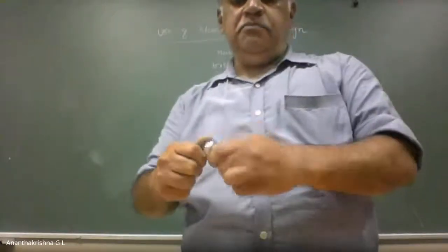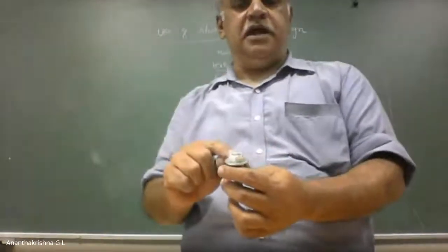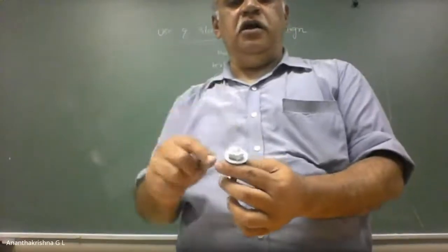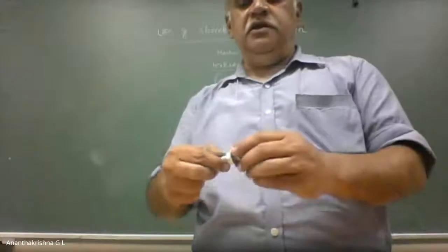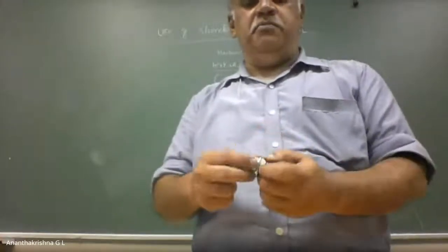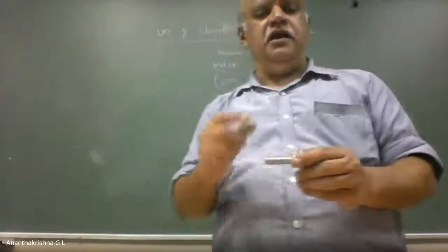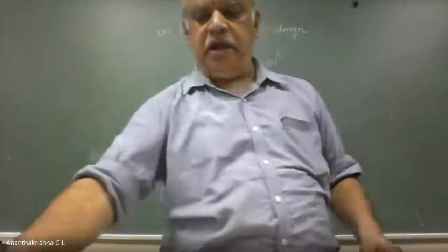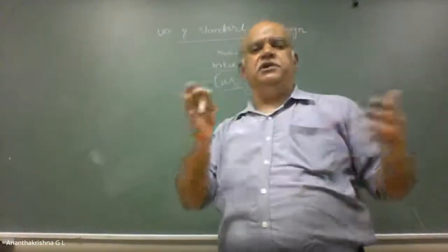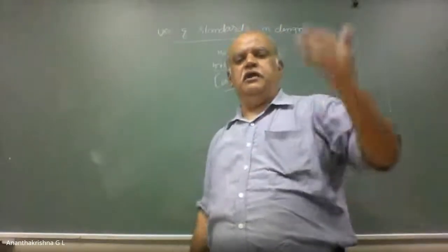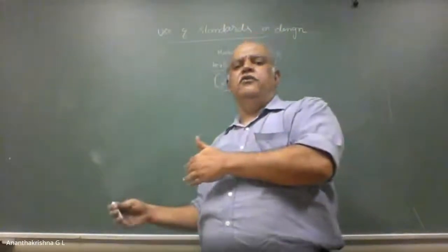And if you see this bolt and nut assembly, it is chrome plated. So plating thickness also has a standard, and you cannot use zinc plating because it is environmentally unfriendly. So you can go for chromium plating or whatever plating. Again, there you have various standards for plating, and you have drawing. You have first angle projection and third angle projection. You cannot have drawing in second angle and fourth angle projection.